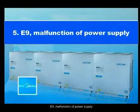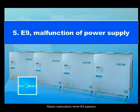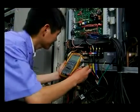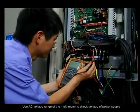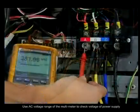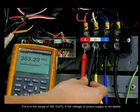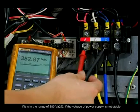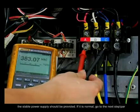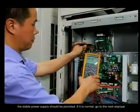E9. Malfunction of power supply. Repair instructions when E9 appears. Step 1. Use the AC voltage range of the multimeter to check if the voltage of the power supply is in the range of 380 volts plus or minus 2%. If the voltage of the power supply is unstable, stable power supply should be provided. If it is normal, go to the next step.